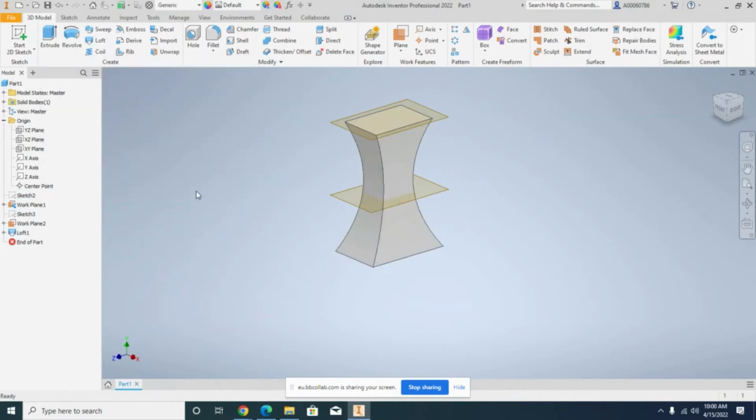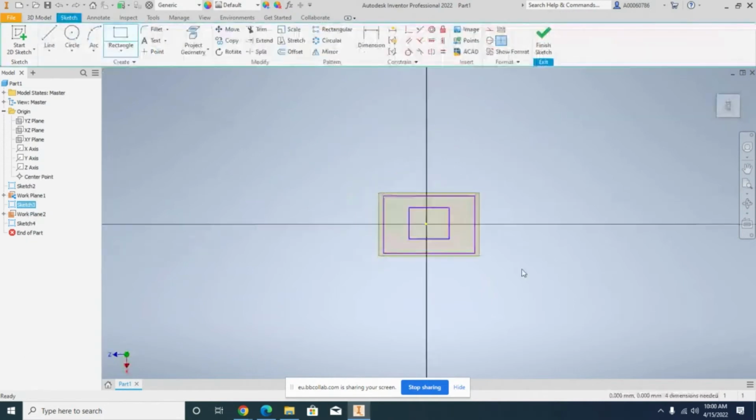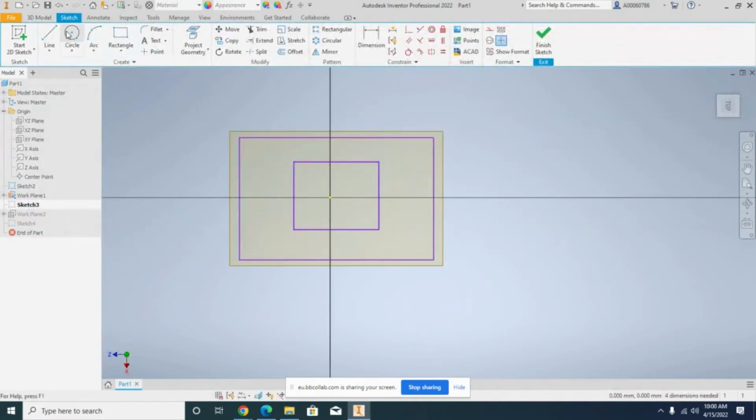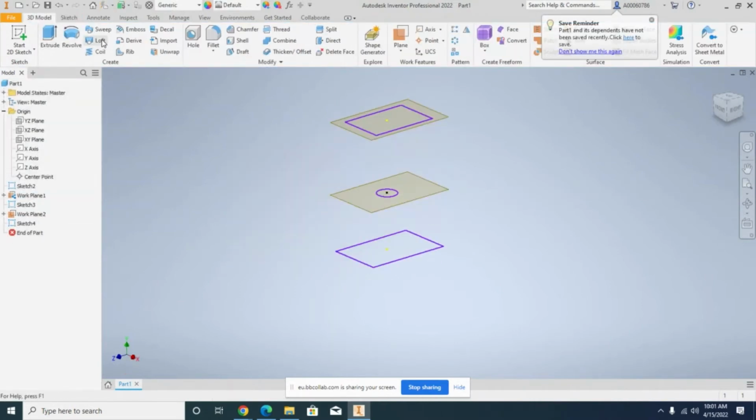That's it. Now we created a new shape that's impossible to create using extrude or revolve or anything. Especially, I want to tell you that loft does not require you all the time to use shapes that are similar. As an example, I can be here using a circle instead of a square.